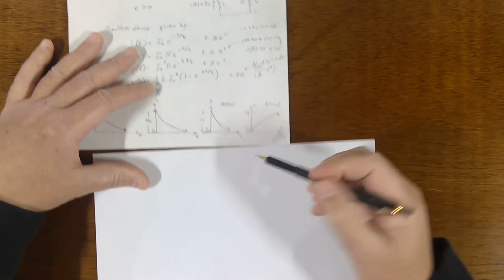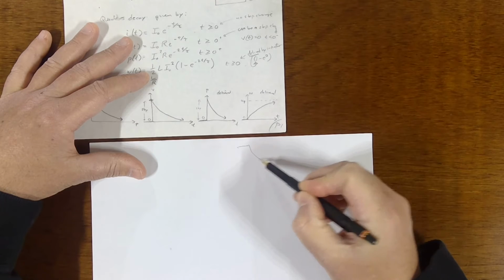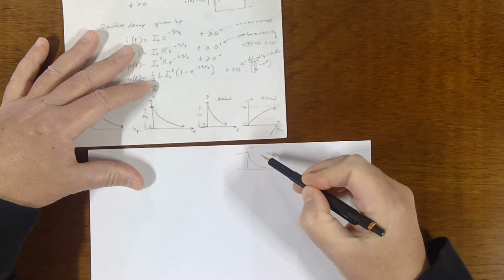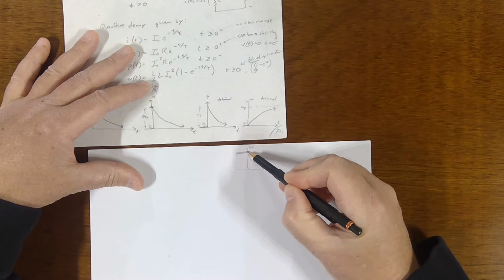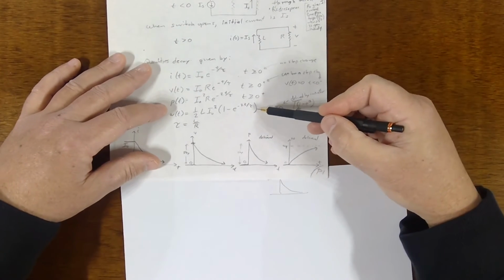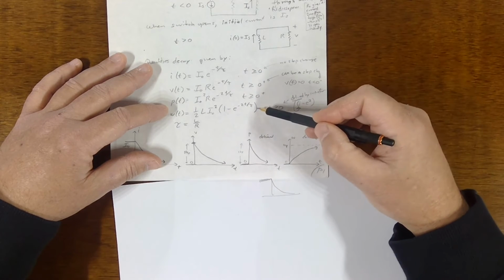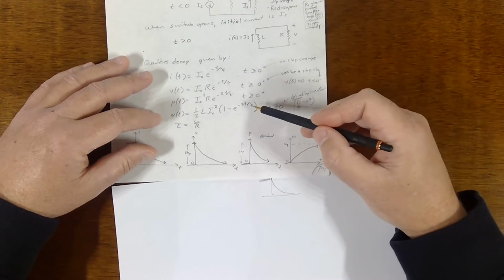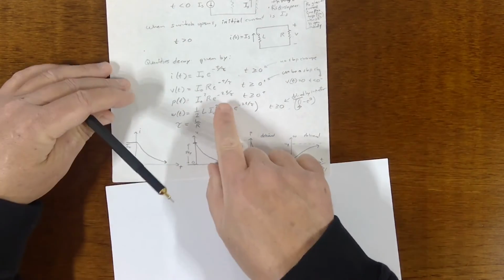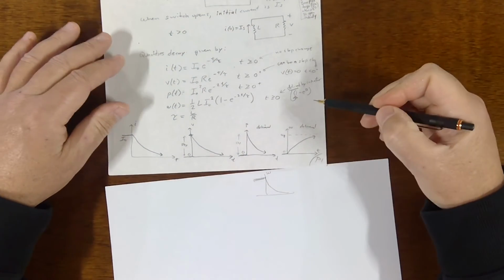You might see a curve that starts like this and then goes down. Then you're talking about the energy in the inductor, right? It's at some initial value. It's charged up, and then the energy is delivered. So this form with the 1 minus e to the minus 2t by tau is from the perspective of delivering energy from the inductor. If you just took out the 1 minus, then it would be from the perspective of receiving the energy from the